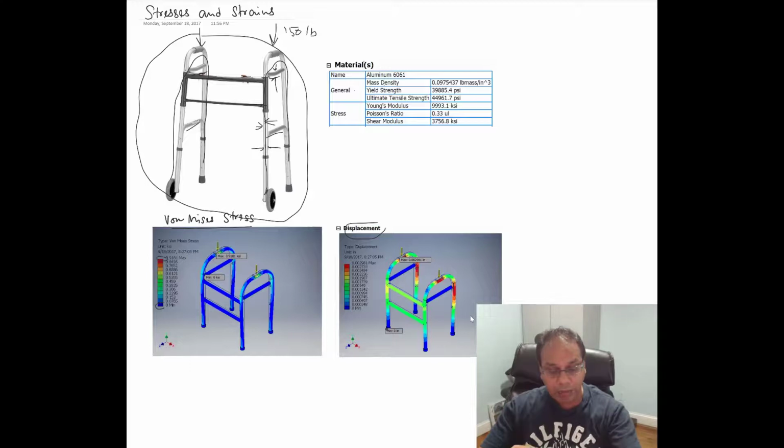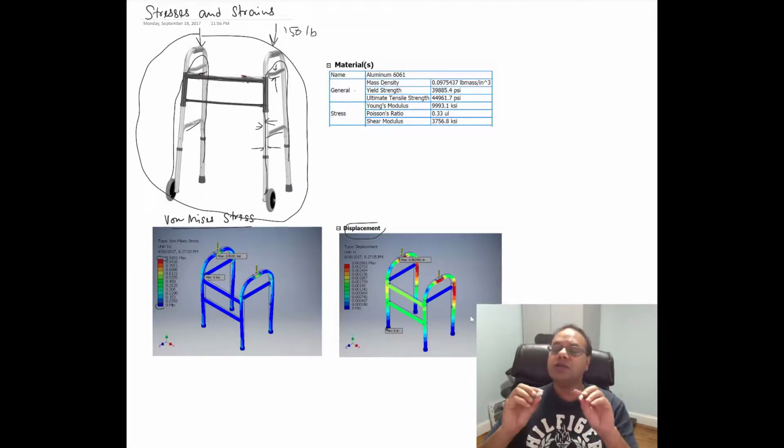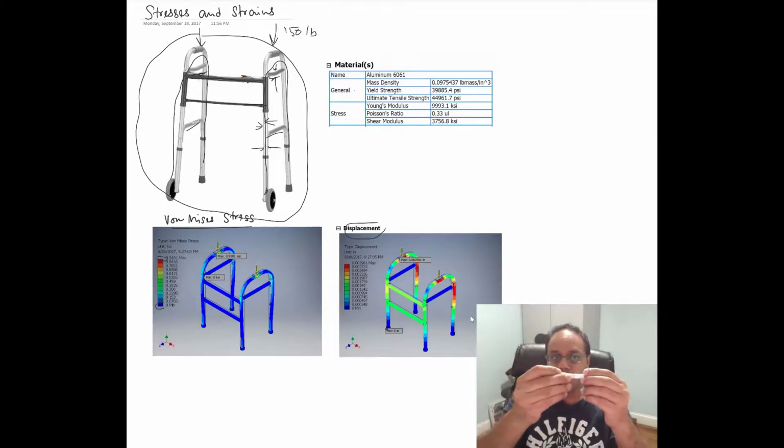This is very different from what happened to the paper clip, because when you apply the loading on it, it essentially was deforming before it fractured. And this is made of a material we call a ductile material. So it appreciably deforms before it fractures. On the other hand, something like chalk, or even any ceramic or some grades of plastic, will not give you any signs of deformation before they fracture. So another thing to notice is that when you look at the fracture cross sections, you see they're almost flat. Okay, they're almost flat essentially.